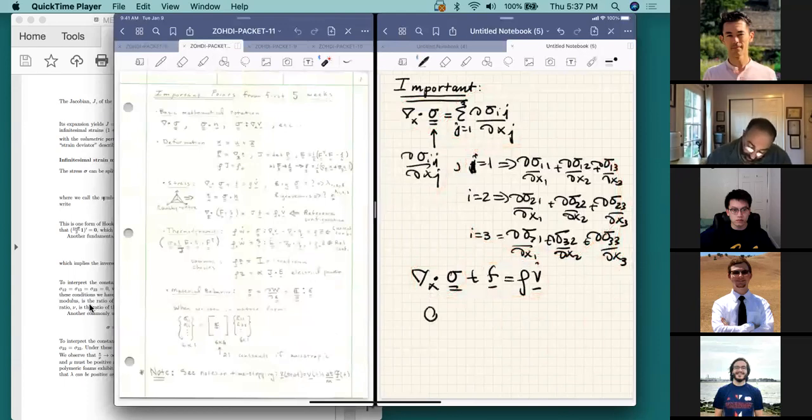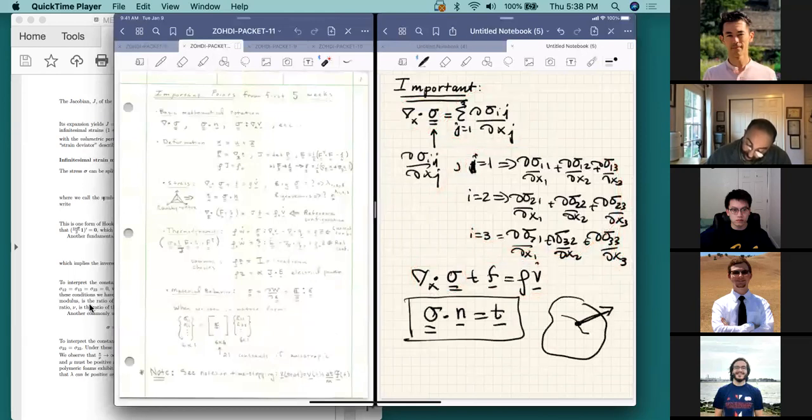Number 2, the idea of the stress dotted with the normal that equals the traction vector, that's extremely important. And really what that allows you to do is that if you come to a body and you say, right at this point, I want to know how big the traction or the forces per unit area are right at this location on this surface. So for example, perhaps I'm putting a strain gauge or some kind of thing at this location here. How you do that is you compute the stress that is at that location. So that's the little stress box, and you multiply that stress by the normal that is shown there. All of that product gives you the traction vector.